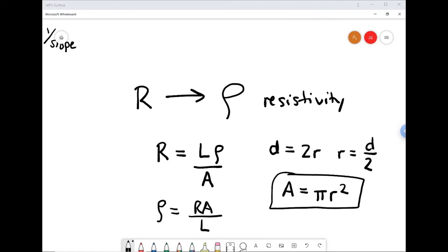All right, so that's an outline of the data analysis you're going to do. You'll take the data that we collected here together, you'll plot it in Excel, you'll do the linear regression analysis in Excel, and then use the results of that to calculate the resistance for each of the coils. There's 2 of them, so you'll do this twice. And then once you have resistance, you'll calculate resistivity and then compare that to the expected value of resistivity for copper, which is supplied in the lab handout materials.